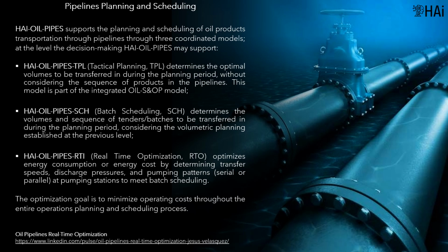And real-time optimization determines transfer speeds, discharge pressures, and pumping patterns, serial or parallel, at pumping stations, to meet the batch scheduling established at the previous level. The optimization goal is to minimize operating costs throughout the entire planning and scheduling process.